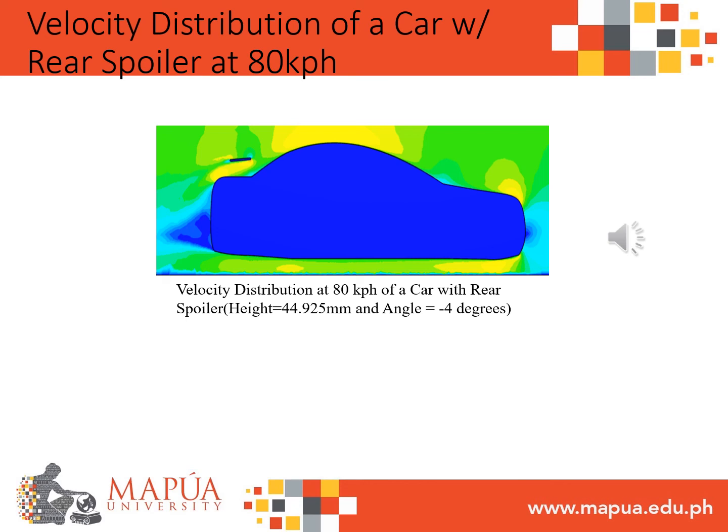So this is the velocity distribution of a car with a rear spoiler whose height is 44.925 mm at an angle of -4 degrees. If we compare this to the velocity distribution of the benchmark, we can actually see a decrease in the low pressure zone, making the drag coefficient of this rear spoiler setup lower.